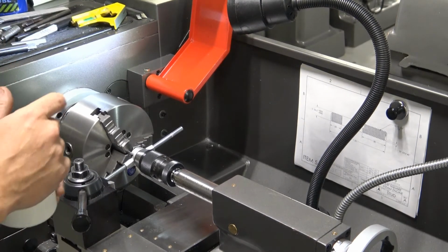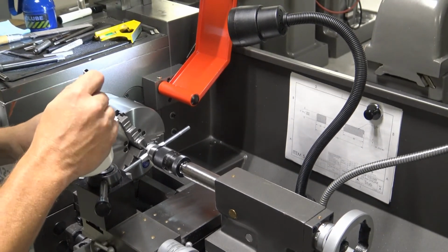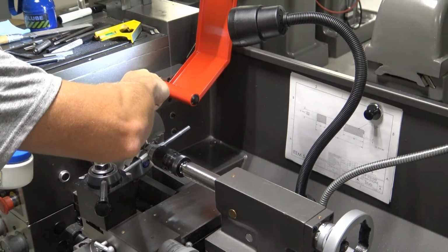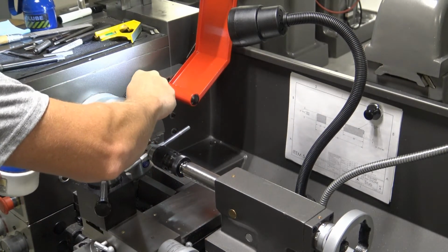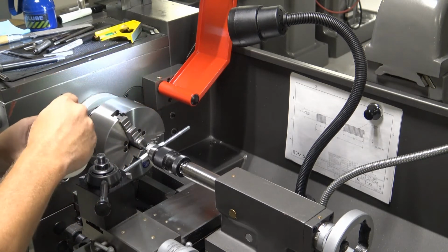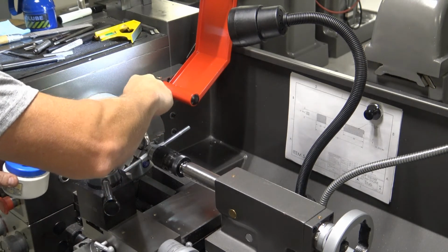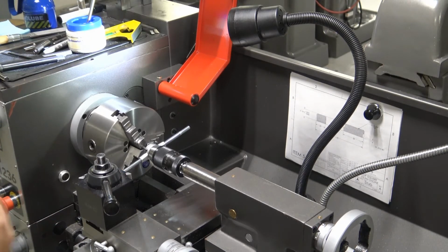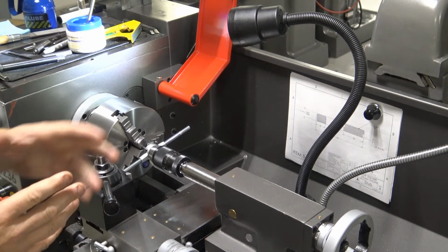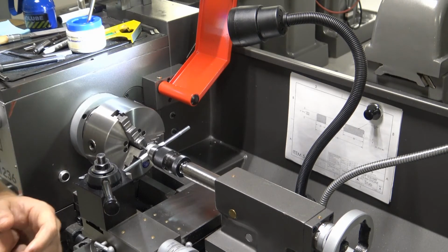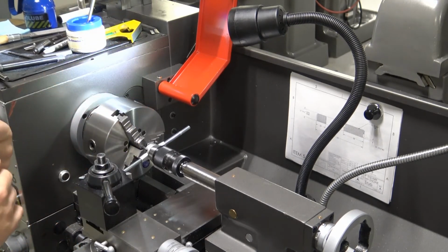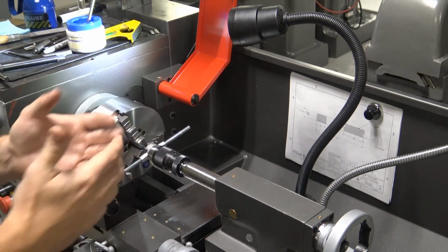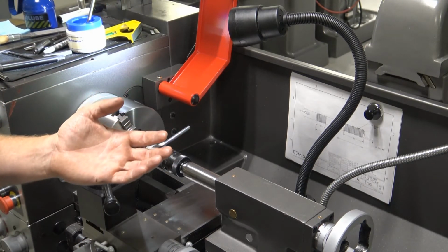When using a die, it's very important that we use cutting oil, all right? So use it. It's there for a reason. All right, so I bathed it in cutting oil. The first thing I'm going to do is the 1/2 inch portion. As I'm turning this, I'm going to be cutting on threads, but how will I know if I'm at a 1/2 inch?